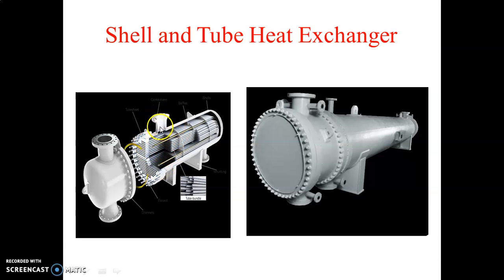At that time you should transfer vapor and gases on the shell side. So these are some guidelines provided for directing the fluid. That means which fluid you have to add on the shell side and which fluid you have to add on the tube side.